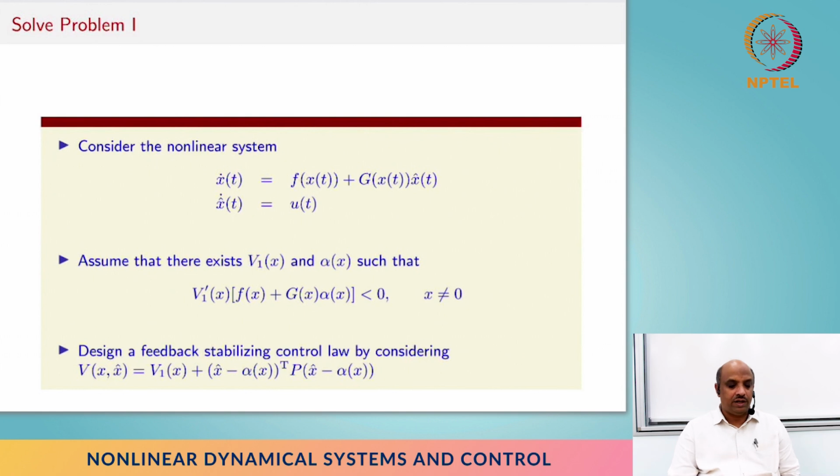Essentially, the idea of what I'm about to show you is how do I solve this? We can try and guess all kinds of Lyapunov functions and probably not reach anywhere, but I'm going to think of it as a very specific idea. Suppose I know somehow the first system can be stabilized through x hat. If you view x hat as an input to the first system, then the second system becomes kind of an integral controller, and then we can find the feedback controller u for the whole system. So that's the logic here.